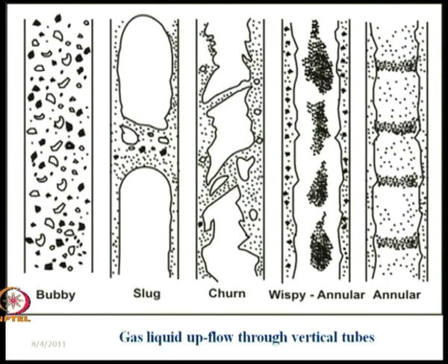Now, the tendency of aeration decreases with tube diameter, as I will show from some photographs shortly. Okay. And what happens is, from the preceding liquid slug, the liquid starts flowing downward as a continuous liquid film along the surface of the bubble, and it forms an annular continuous wetting film between the tube wall and the bubble surface.